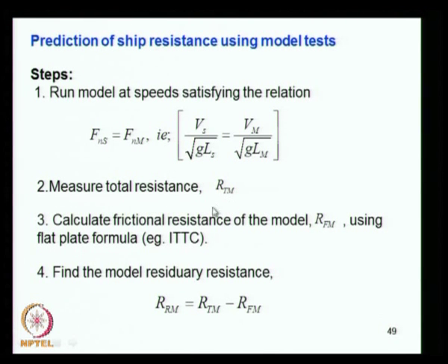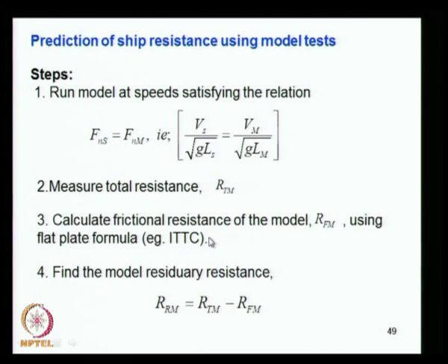Now what you do is you calculate the frictional resistance of the model, RFM, using the flat plate formula, maybe the ITTC formula. We have already discussed this before: what the flat plate formula is, what the different formulae normally used are, and how the experiments are done, which we discussed in one of the classes. Here ITTC has come out with a simple empirical relation to represent the frictional resistance coefficient, from which you will be able to find the frictional resistance of the model.